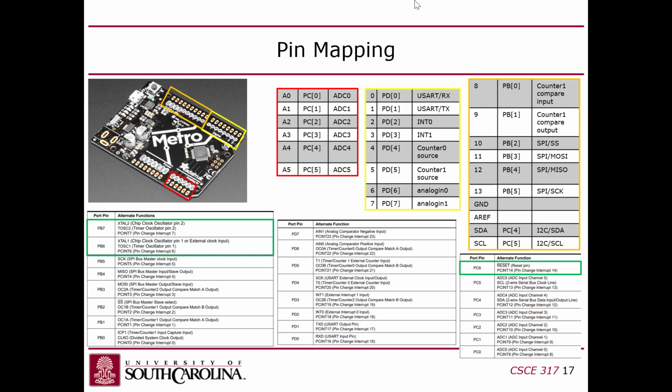The orange, yeah, SDA. So these guys are labeled SCL, SDA. That's part of I2C, or the two-wire interface, which I believe match up to PC4 and 5, which also are over here on the analog side. So, yeah, Charles will verify that. It might be a typo, but I think they may just be shorted.